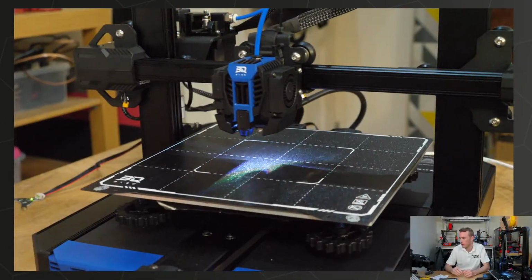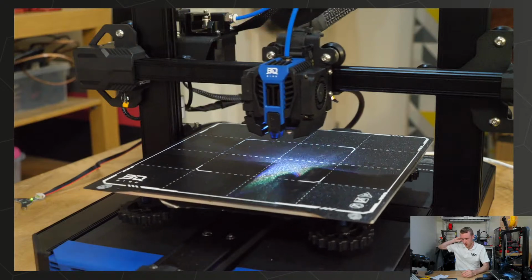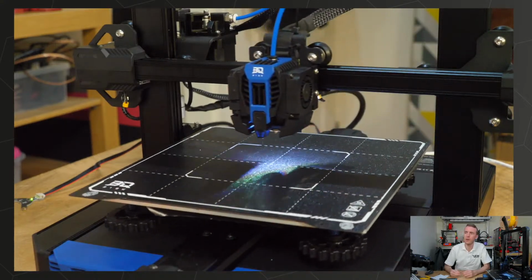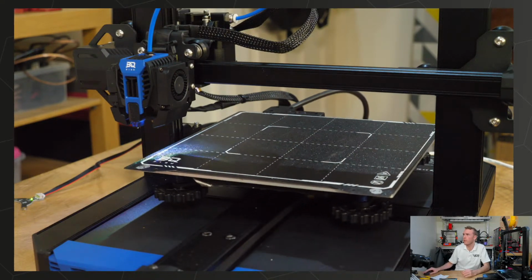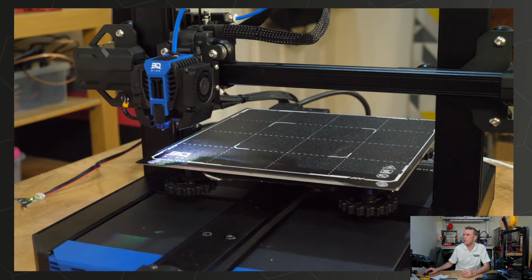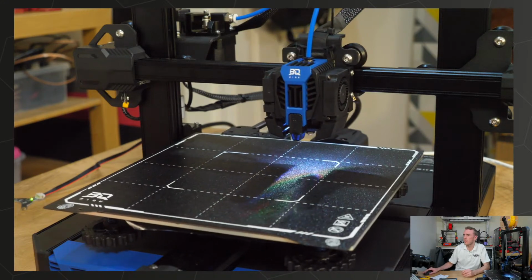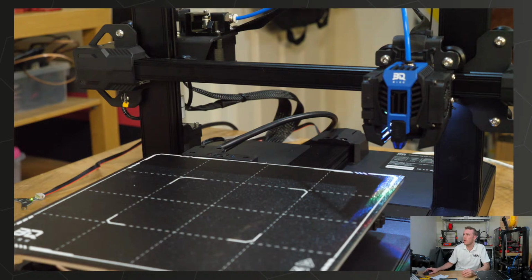Oop, wrong one. No, not up to max speed. Ooh, it looks a bit framey. Why does it look weird and framey? So that was these settings. It looks like microsteps is set on the axis configuration rather than the run currents. Z is a bit lower, extruder is also lower.